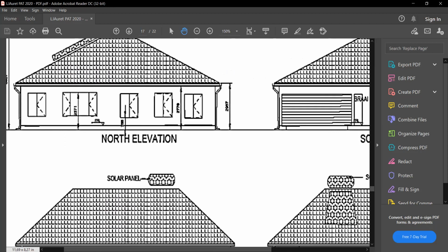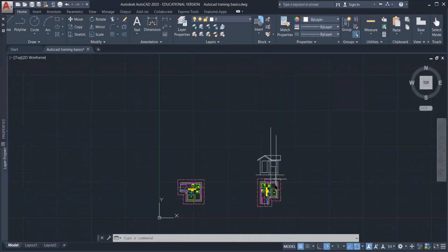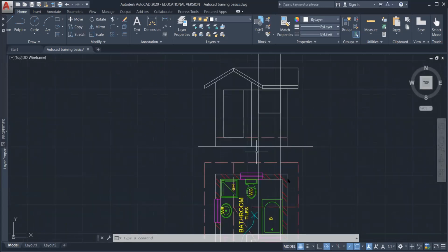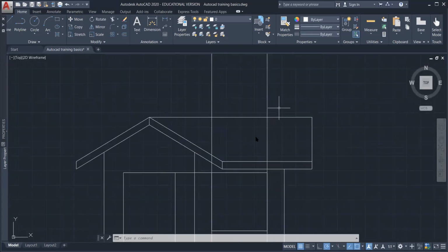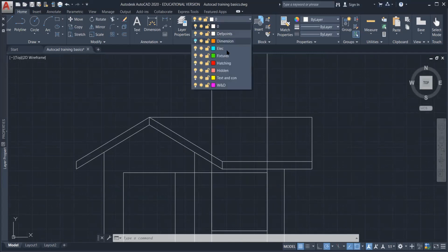Okay, so let's go back to the drawing. Just going to flip over again. Stop sharing, share. Okay, so the secret to starting your elevation is to use your floor plan and project it upwards. Now, for instance, if you want to add detail to your tiles, let's change it to hatching again.